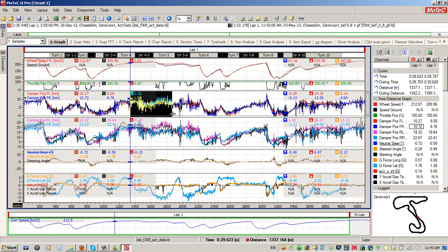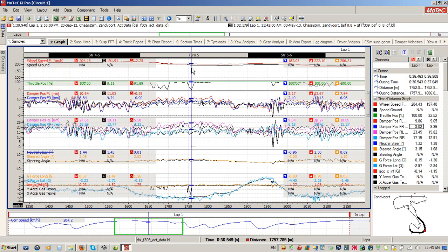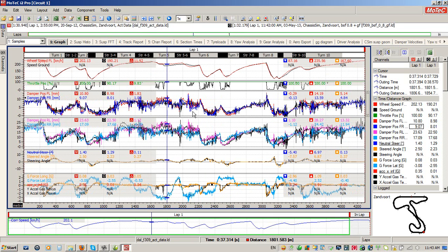Another thing that you could do at this point as well, particularly if the bumps were going out of control, is to manually go into the edit variable grip scale factors and just tune the bump scale factors there, just to bring that corner speed into line. But as a general basis, I would look at something like that and figure, you know what, I'm pretty much good to go to do my simulation work.